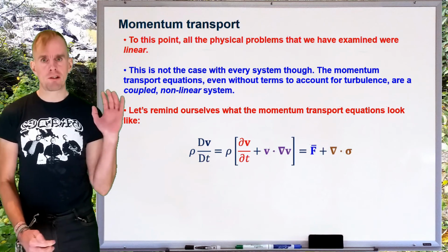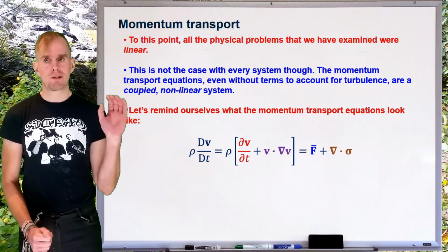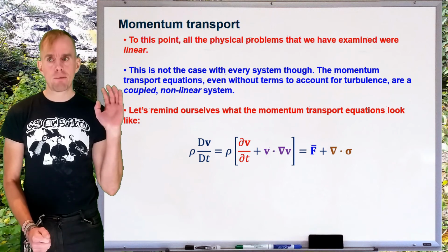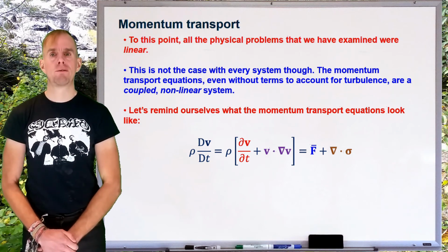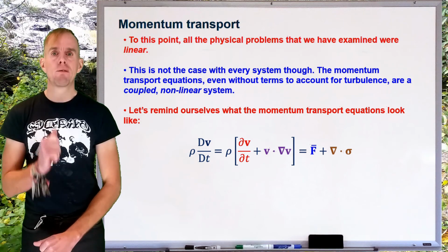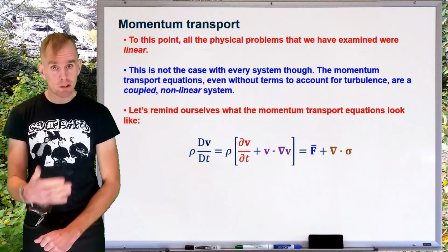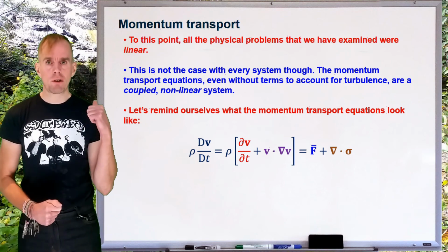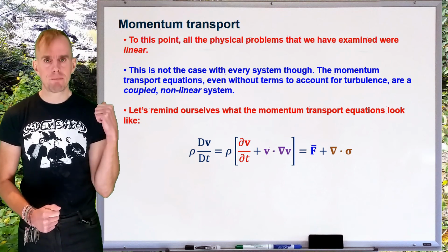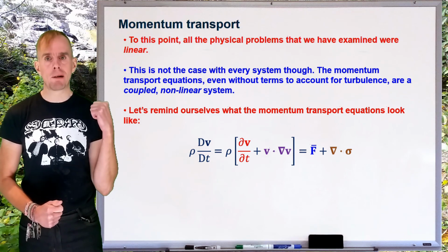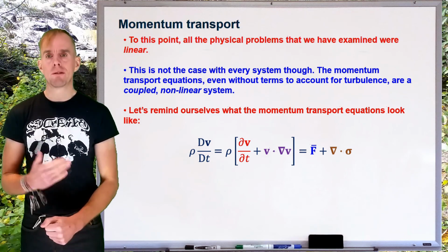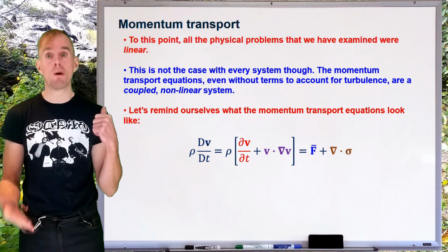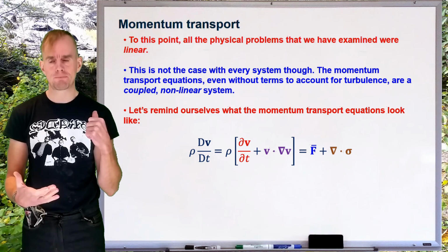Now on the board I've put a single equation, but the first thing to note is that this is a transport equation now involving a vector quantity. If we look on the left hand side at that total derivative, big D by big Dt, it's of a vector field V, not of a scalar quantity like T, temperature, or C, concentration. And so this equation now represents not one, but as many equations as we have spatial dimensions. So my velocity vector here might be 2D, or it might be 3D. So this will represent either 2 or 3 transport equations.